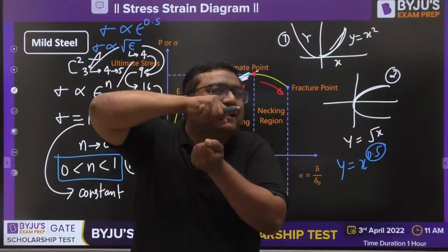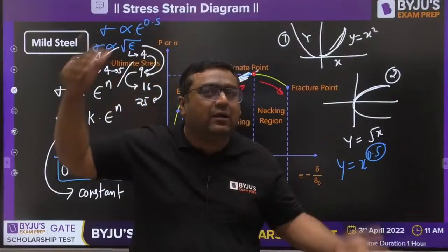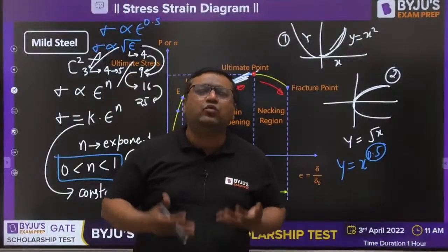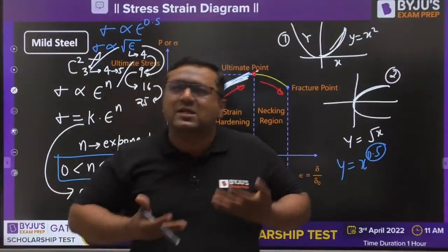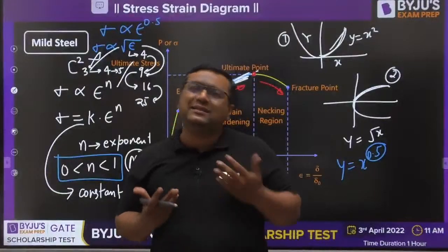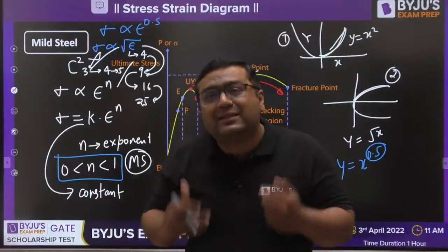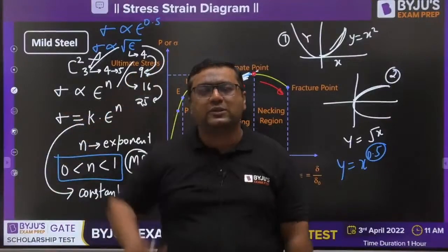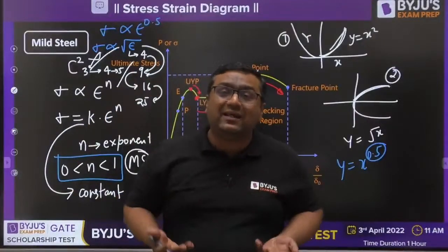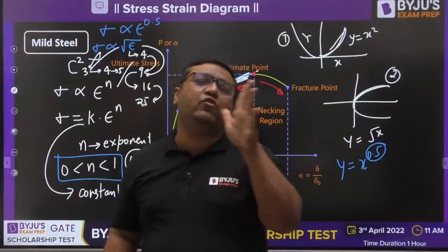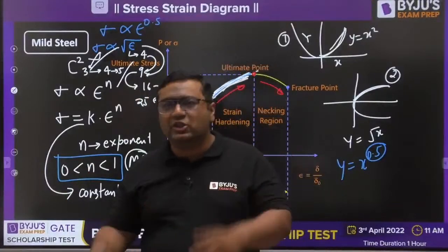When I am expanding it 3 mm per second, sometimes the workpiece would show more resistance, sometimes less resistance. When the workpiece shows more resistance, I would be applying more force. When it shows less resistance, I would be applying less force, because my target is a constant deformation rate. So that is how the machine is working.